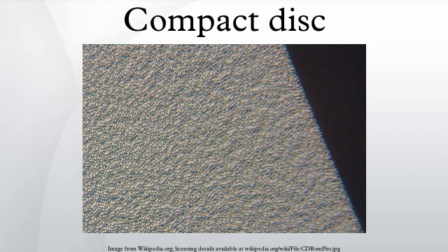Over time the dye's physical characteristics may change, however, causing read errors and data loss until the reading device cannot recover with error correction methods. The design life is from 20 to 100 years, depending on the quality of the discs, the quality of the writing drive, and storage conditions. However, testing has demonstrated such degradation of some discs in as little as 18 months under normal storage conditions. This failure is known as disc rot, for which there are several, mostly environmental, reasons.